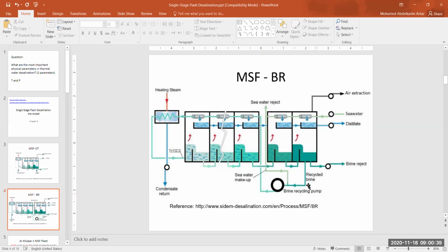This is one benefit. The second benefit is that we are recirculating the brine at this temperature, the 40 degrees centigrade. So when it comes here at 40, it might leave here at about 65. Actually, in actual cases, it might leave closer to 80 or 90 degrees centigrade. So have you reduced the quantity of energy needed here to reach the top brine temperature? What is the penalty that we have to pay?